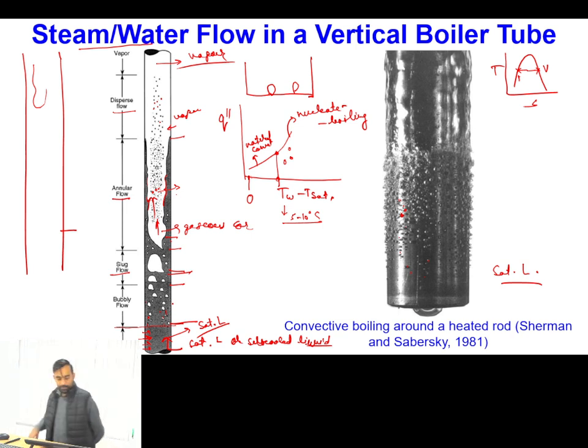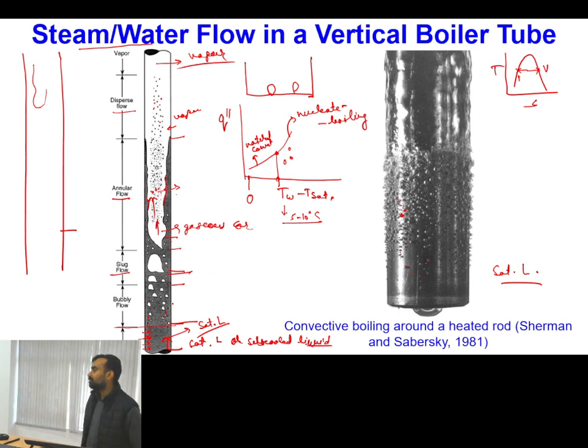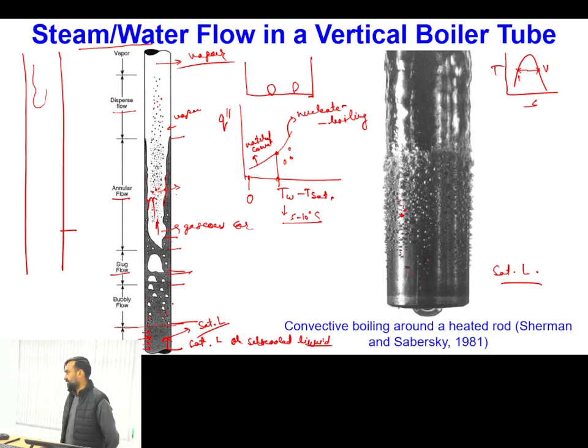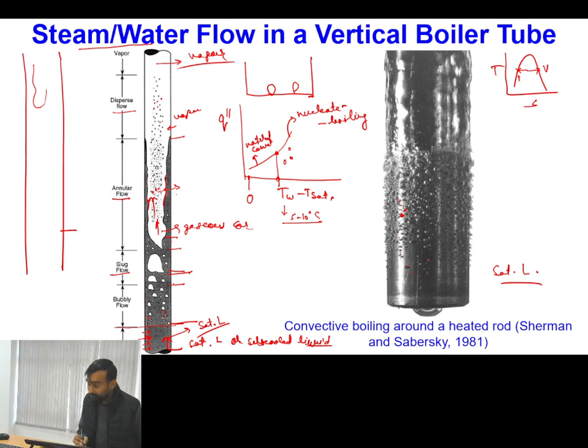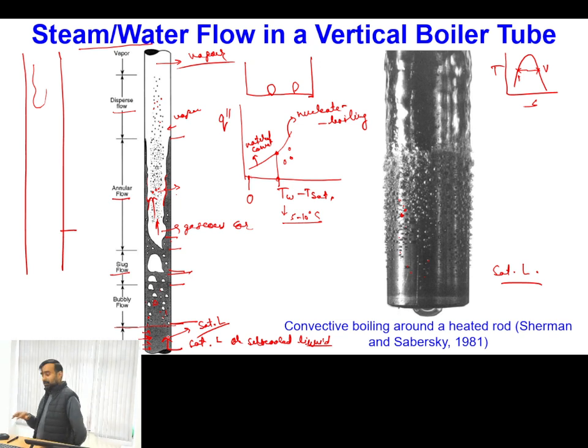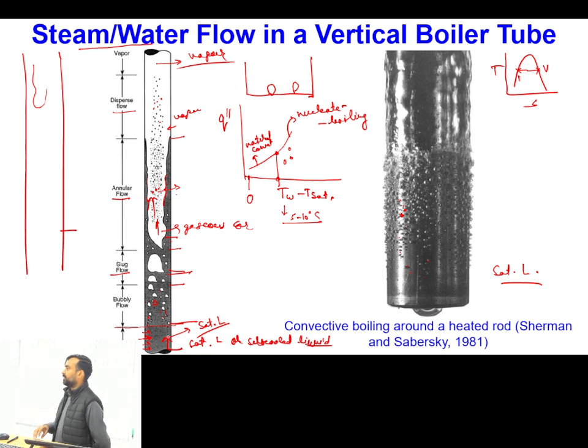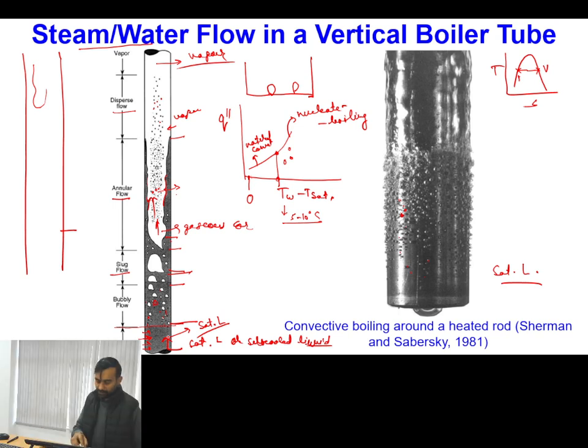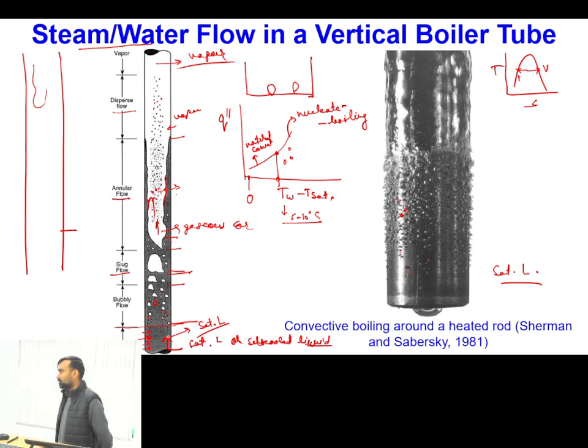You have to use different pipe segments to see what type of volume fraction is present in that segment. Of course, the flow will not be fully steady, since the interface or bubble formation in this pattern can be dynamic. But on the basis of global parameters like volume fraction, this flow can be considered steady. The volume fraction value in this zone may remain almost consistent with time.